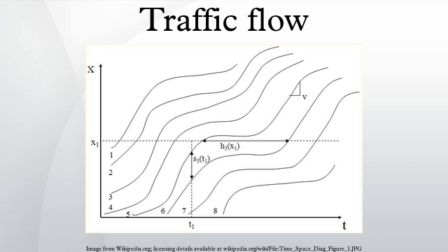The authors included an example of such a graph. This flow versus concentration plot is still used today. The authors used this flow concentration model to illustrate the concept of shock waves, which slow down vehicles which enter them, and the conditions that surround them.